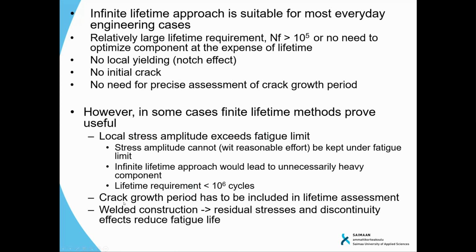Or if we need to include the crack growth, then of course we need to go for fracture mechanics. Or if we have welded constructions, because there are always residual stresses and there are discontinuity effects that will reduce the fatigue life. So for a welded component, basically, you could say that you never achieve infinite lifetime due to these reasons. It might be very long though, but it's safe to assume that there is no infinite lifetime for welded constructions.